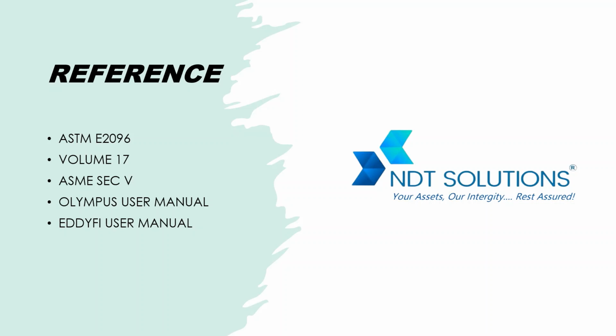Mainly all the materials are available, so the only thing is we need to go through them and read them. Here we have given the references from where I took all this, and you can also go through them. ASTM E2096, ASME Section 5, Article 17 also, particularly for the RFET. And whichever equipment you are using, if you are using Olympus, then go through the manual.